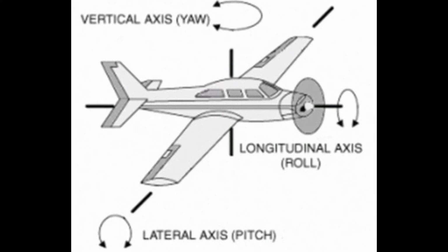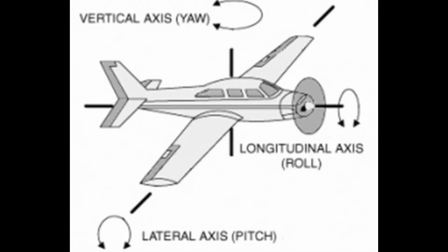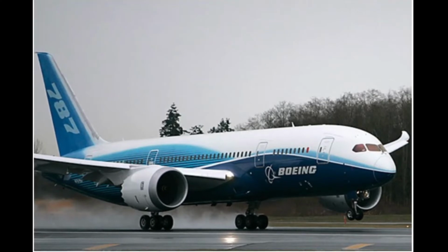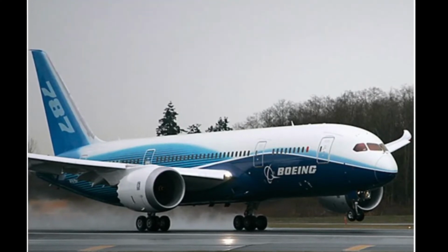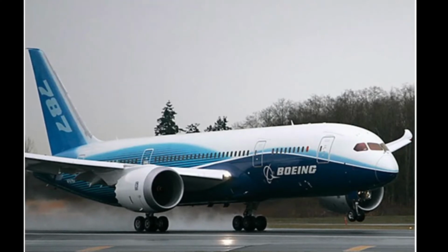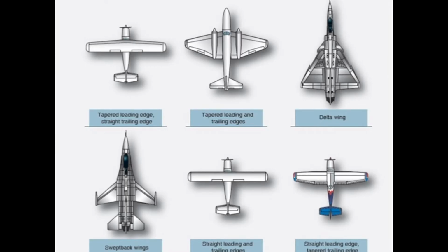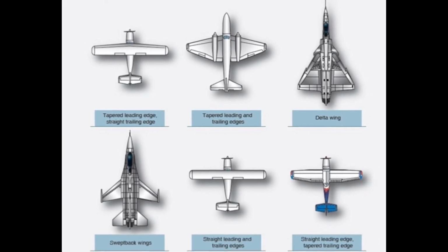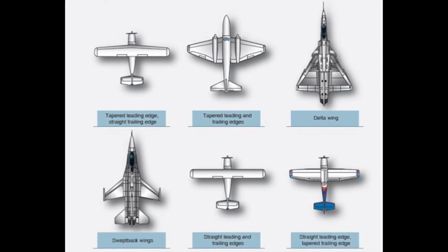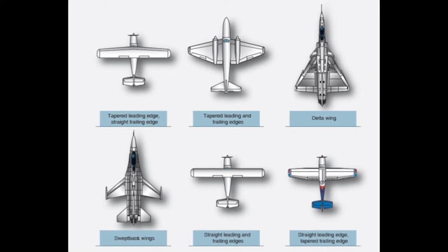Some of these stresses are oscillatory, constantly varying about a fixed value, in nature. This introduces another type of stress called fatigue stress, which can then worsen the corrosion of the structure. This is particularly the case for metallic structures. Composition and components of the aircraft wing structure. The structure of the wing is such that adequate support is provided and loads can be transferred easily between the wing elements to preserve its structural integrity.